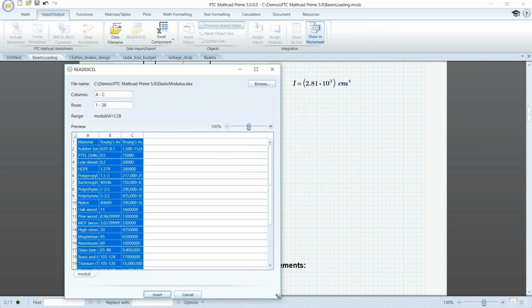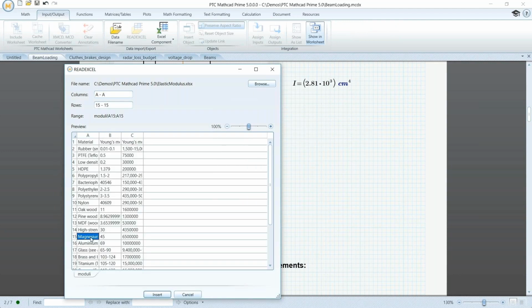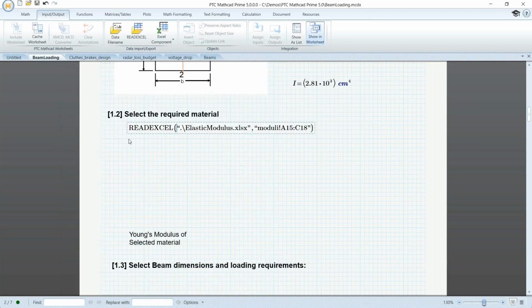So you don't want to have to retype in all those Excel values that you have, and you still want to be able to use Excel for its capabilities of a spreadsheet, but maybe combine that with Mathcad so you can see all of your functions all out in the open instead of hidden in a cell. So we don't have to throw away or retype any of our Excel. We're just going to grab the rows and columns that we'd like to use within our Mathcad workbook. So it's going to read the Excel sheet straight from there and pull it in whatever that data is.